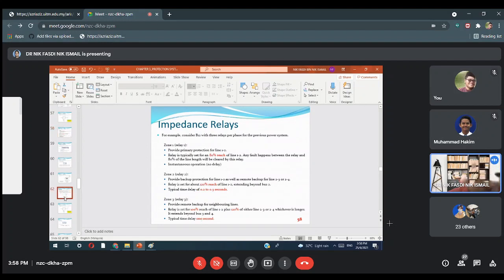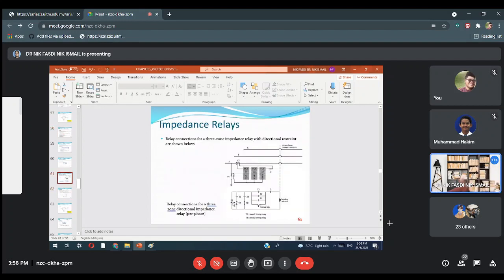So back to this diagram, it has time delay here, T2, T3. T2 represents zone 2, T3 represents zone 3. Okay. So for example, if Z2 turns on but the time delay has not elapsed, it does not turn on either; it is in series, okay.